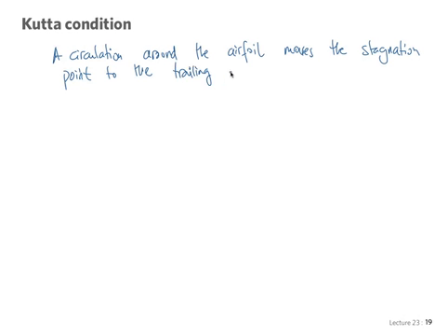We must have separation at the trailing edge, there is in fact a slip layer in the back, which is called a vortex sheet, because basically the flow here has different velocity than the flow here, and so there's a slip velocity in that layer just at the trailing edge.